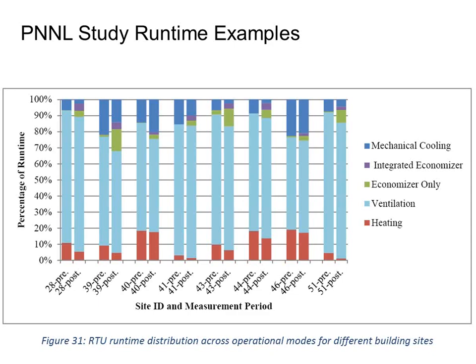So we only have one damper on a rooftop unit. He's going to open to some ventilation position. For right now, let's say it's open at 20%. And he opens to that position and runs 20% outside air all day long, no matter what. Then, if he wants to go into economizer mode, meaning free cooling mode because it's nice outside and I don't want to run my compressor, then I modulate the damper more from 20% to something higher during that cooling cycle.